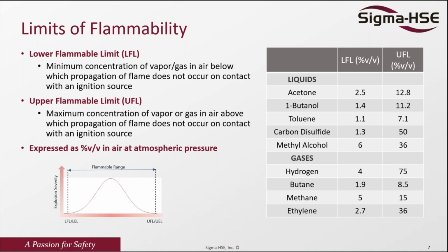In between them is where you can have ignition, and there are several parameters that can interfere with the flammability range, such as oxygen and the addition of additives. This is not the topic for today's discussion, but just for you to know. In between the flammable range, there's always a point where the flame is at a stoichiometric concentration, where we have an optimum, enough oxygen and enough fuel to ignite and release the most violent explosion.